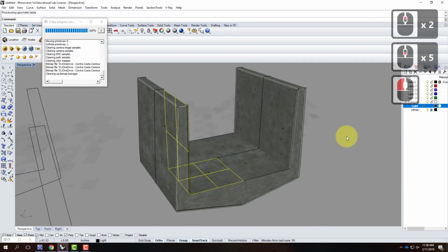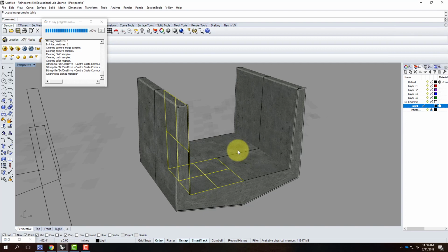Once you have your object set up, you're going to go ahead and render it, and then you'll post that by the end of class today. This is very much about the skills and the practice of doing the chamfers, learning how to zoom in and zoom out, recentering your objects, doing the trims, all of that sort of thing. So I expect you to actually go through and do all the corners rather than do the shortcut method that I did with one set of corners. But I also want to show you the strategy that if you look at an object and it's symmetrical, do part of it and then mirror it later on, because that will definitely help you model faster.